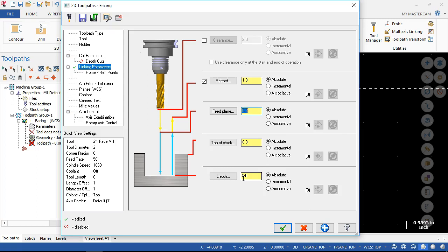When we go to the control and I tell it that there's a wear value, or a work offset, I'm going to shift everything down at the control. I'm going to manage it at the control. So it keeps the values clean in the program, and we make the adjustments at the control that we need to bring the stock in.